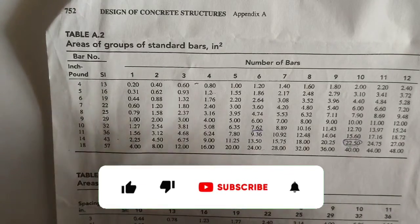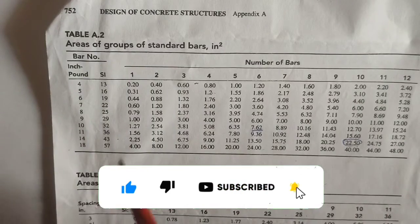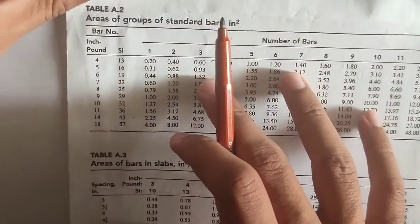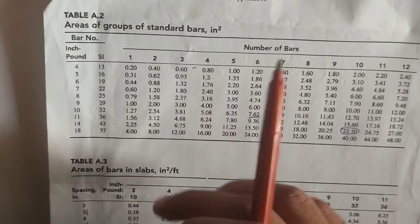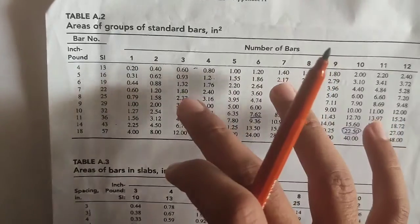It's Abdullah Maqsood. Today we are going to discuss briefly the areas of groups of standard bars in inch square. You have these two tables, and you have calculated your reinforcement area for a beam or for your slab, and then how will you read these tables to get your exact figure of bars.